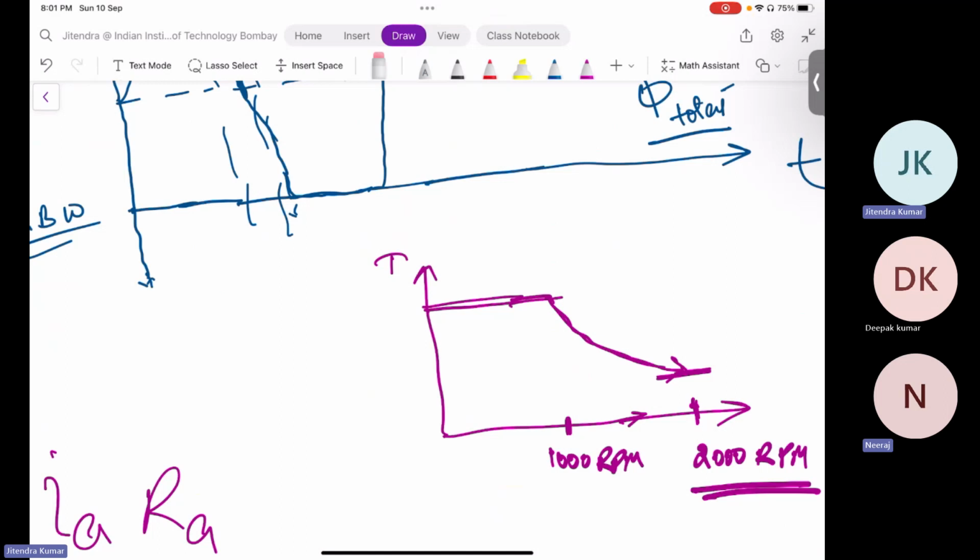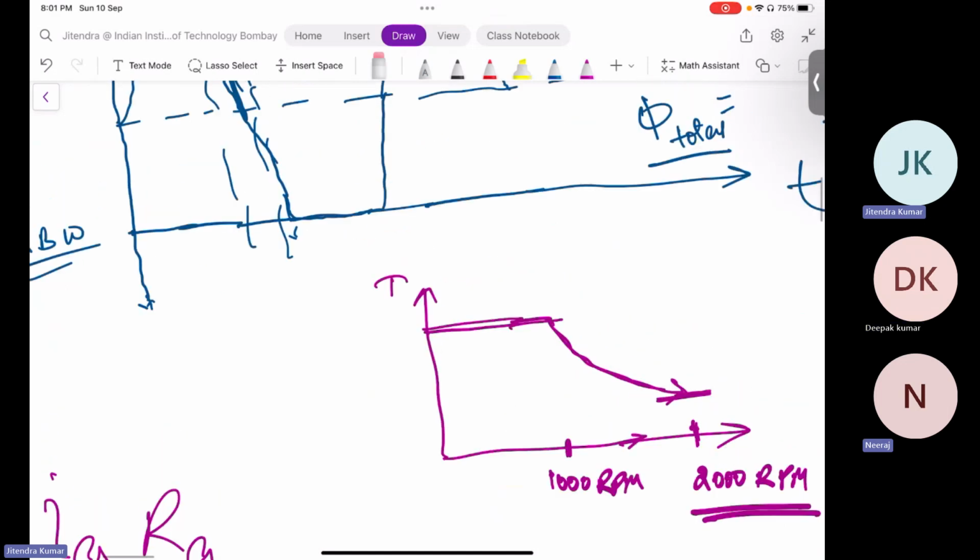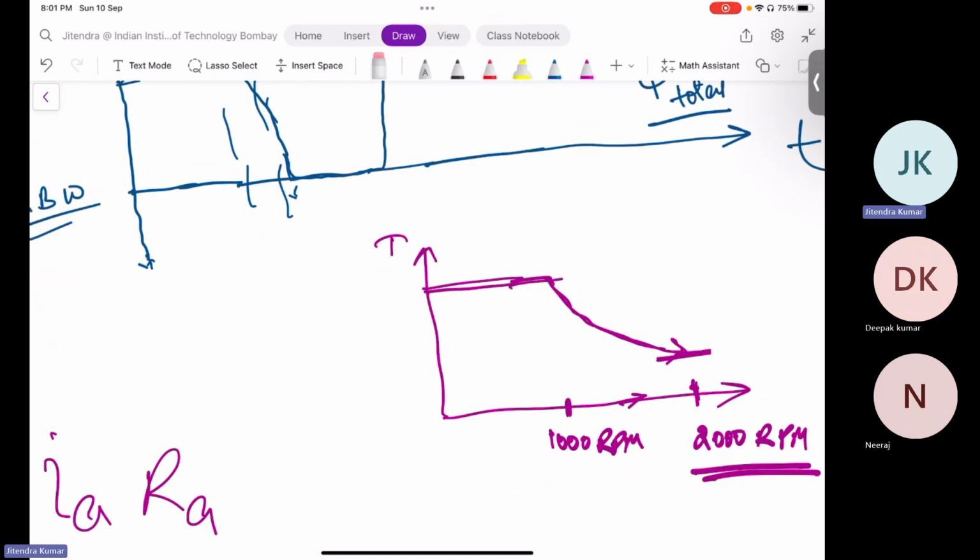Okay, sir. So all these new electric vehicles, the small autos that run on battery, they use BLDC motors, brushless DC motors. They are provided DC current, but with the help of power electronics converters. And the cars have PMSM, sinusoidal AC motors. It's not that you cannot use a DC motor there. It is just that AC motors are very much advantageous in such kind of application.